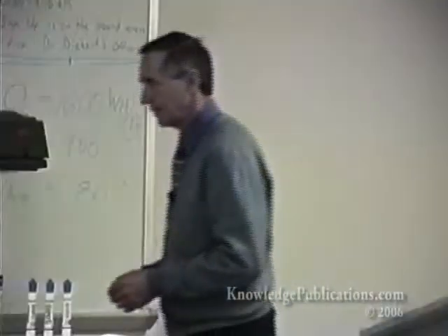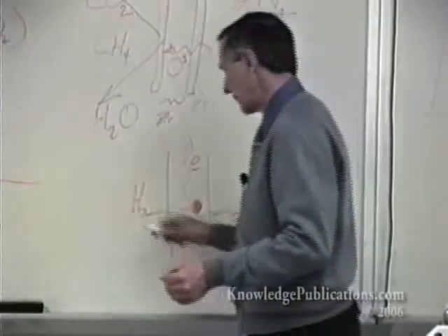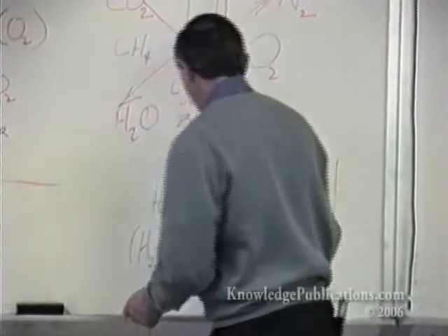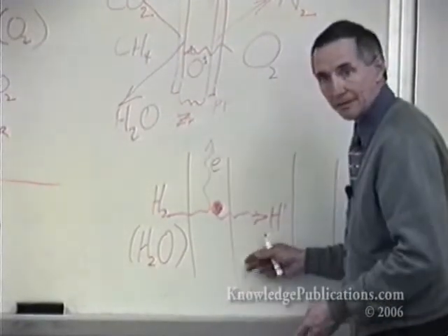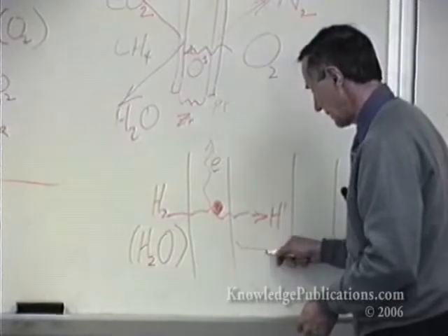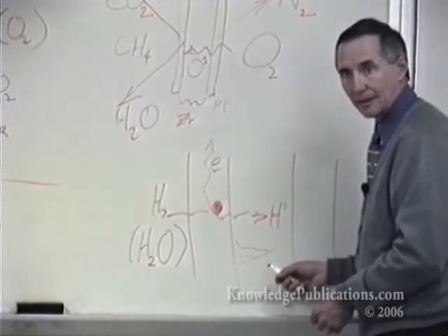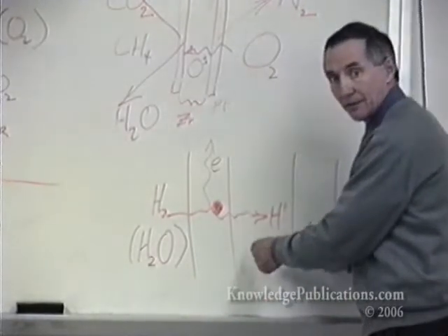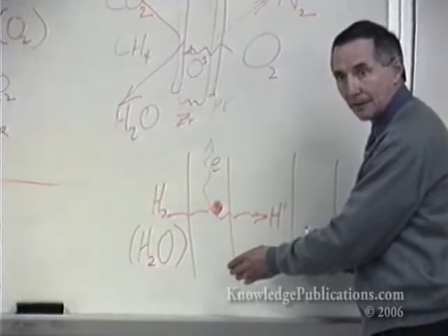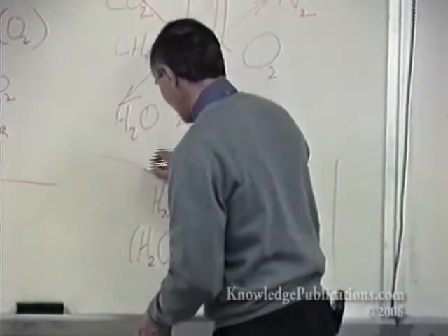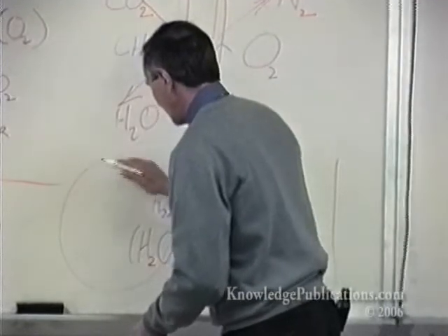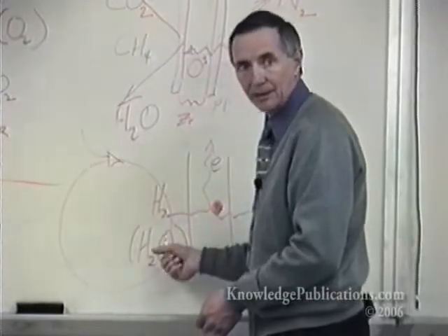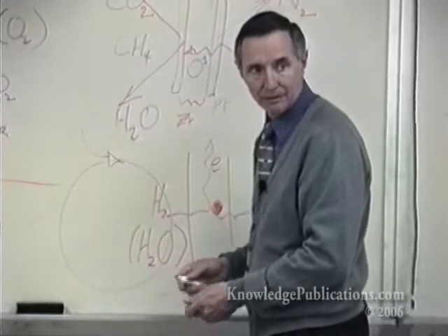An important subsystem for this type of fuel cell is to supply this side with moisture so that the membrane doesn't dry up and crack and let hydrogen get through the cracks. And so that even before it would dry up and let hydrogen get in, it doesn't lose this capacity for being a good conductor for ions. So you'll need a way to circulate the hydrogen. You need to input hydrogen and circulate the moisture so that you maintain a humidity that is adequate for the membrane purposes.